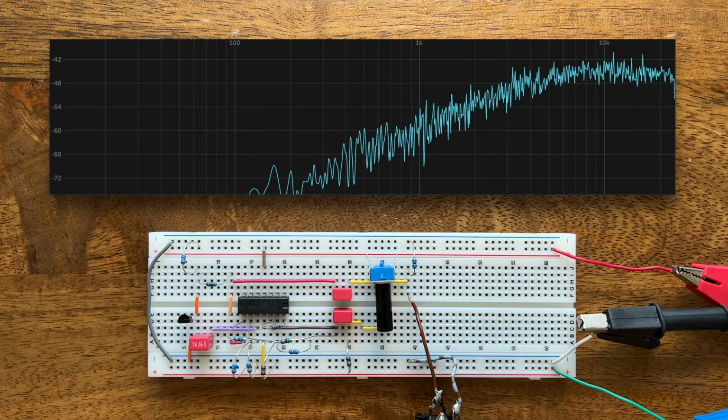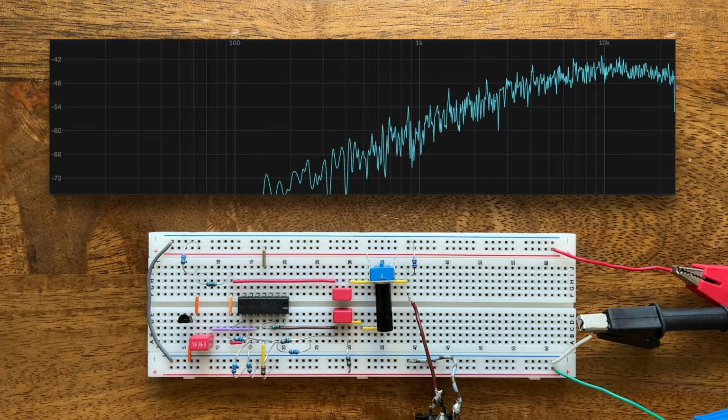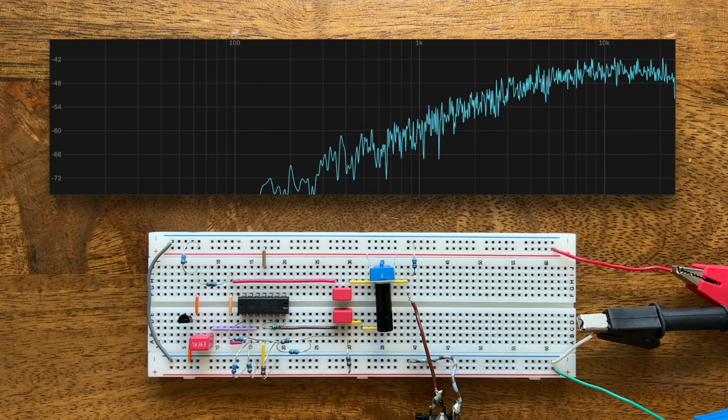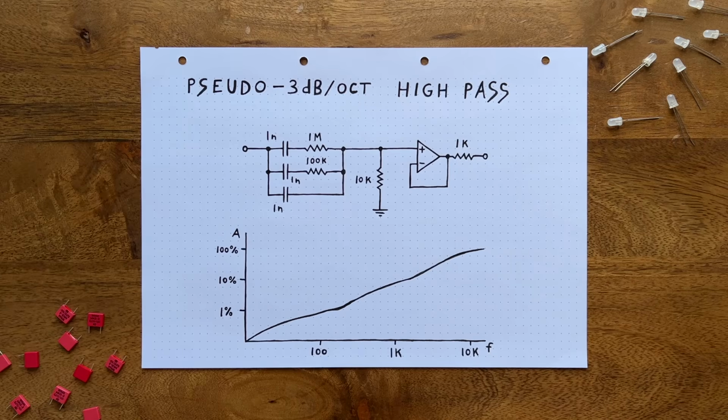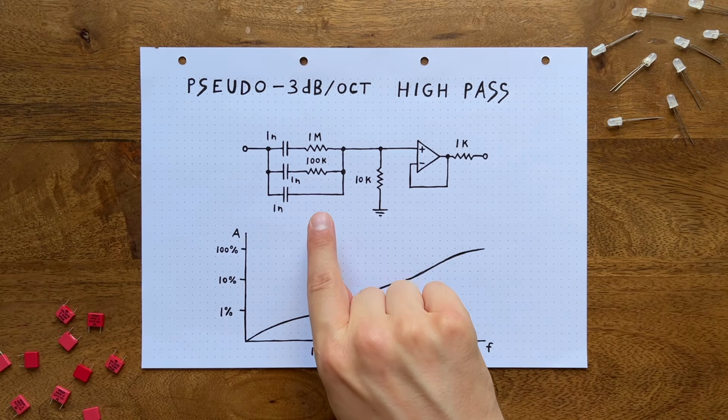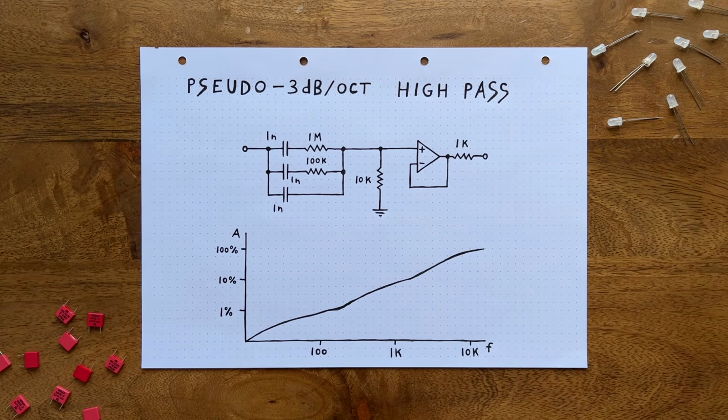As you can see, we're able to set an upper volume threshold for our filter's output, while moving the cutoff point to the left, just as expected. Cool, so we've got the single slope limited high pass down. Next, let's go for multiple slopes. Just like before, we simply have to add in more capacitor-resistor pairs in parallel with the original one, and fine-tune their values until we get a result like this.